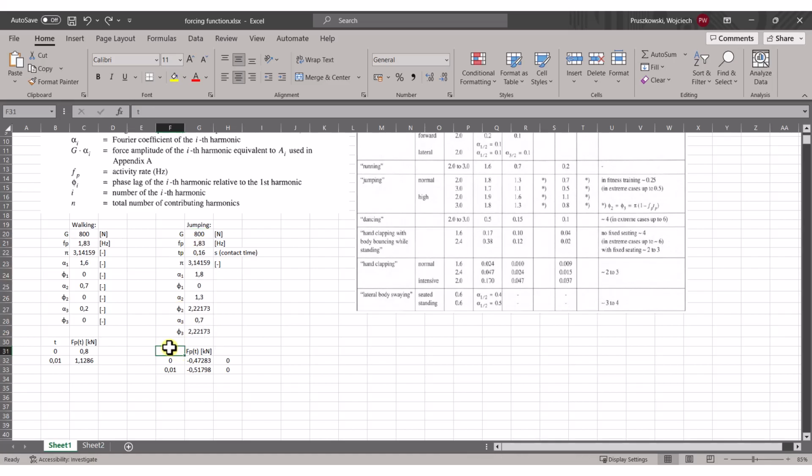The only thing remaining to do is to select an appropriate time step and calculate the values. We will use these time marks and resulting values as data pairs to assemble the function in SOFiSTiK. Therefore, the selected time step has to be small enough to provide enough fidelity into the function over time. I have selected 0.02 seconds as it matches the time step I'm planning to use in the analysis, and it should provide me with good enough accuracy. Let's calculate the function for a time span of 5 seconds now.